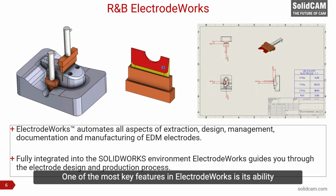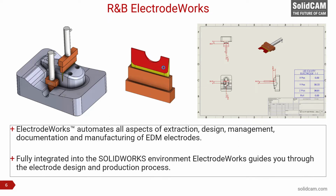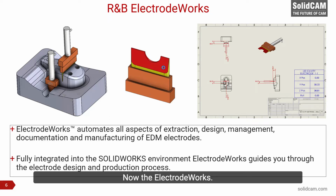One of the most key features in Electrode Works is its ability to apply spark gaps directly on the model, thereby eliminating the need for creating what we do in the manufacturing for negative machining. You don't have to apply any negative offsets when you're doing the machining down the line. So Electrode Works has this ability to apply spark gaps straight away. Fully integrated with SolidWorks environments, Electrode Works guides you through the entire electrode design and production process. Right, we are going to see again now the Electrode Works.